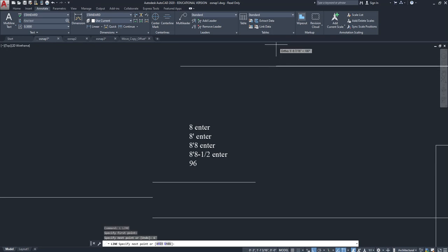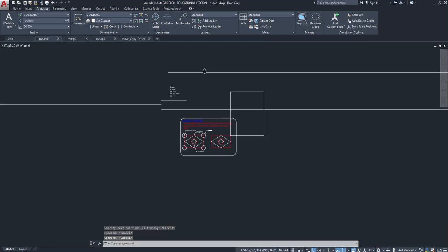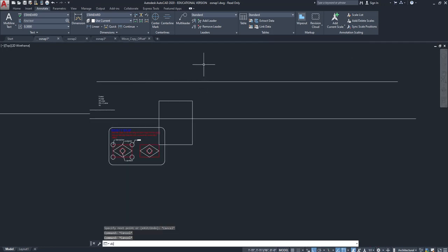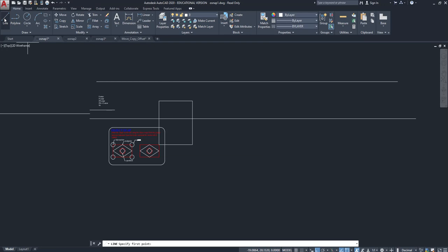I get something happening, right? And if I hit escape and I zoom out and I want to measure this, DIST, enter, click, click, I see down here it says 6 feet. Great, that's wonderful. If I had accidentally forgotten to change these units and I left them in decimal, because I have set AutoCAD's drawing space to recognize decimal units, if I try and input feet and inches, which is a different system, click, move in the direction I want to go, I type 6 foot, enter, nothing happens, right?